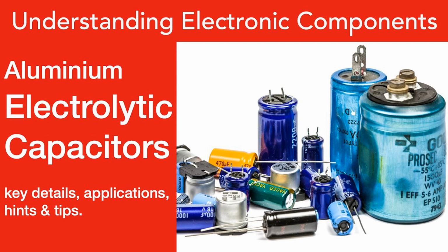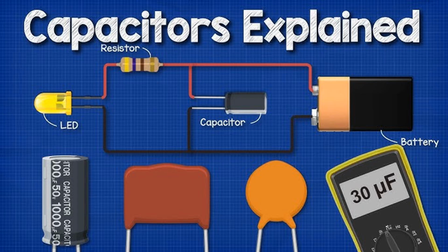How capacitors are used for voltage regulation. Principle: stabilizing voltage. Capacitors can smooth out voltage fluctuations by storing and releasing charge. When there are changes in the load or input voltage, capacitors absorb or provide charge to keep the output voltage stable. Filtering ripple: in power supply circuits, capacitors filter out AC ripple and noise from the DC output, ensuring a steady and clean voltage supply.